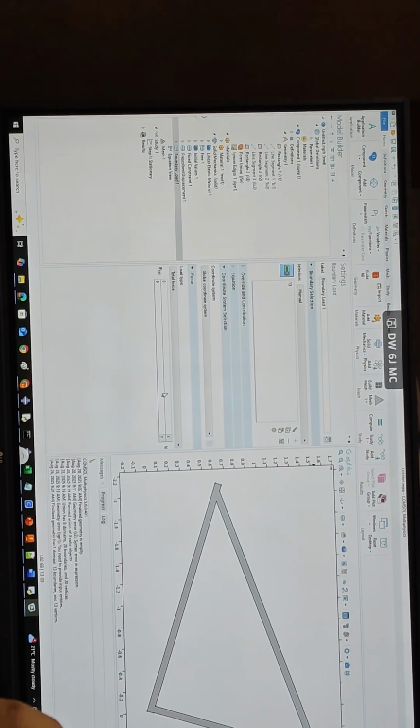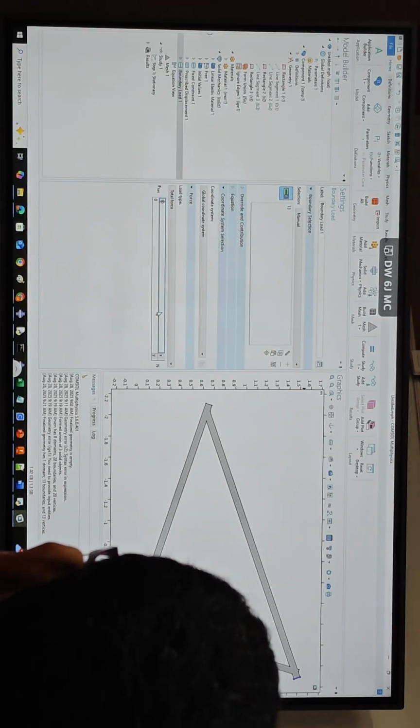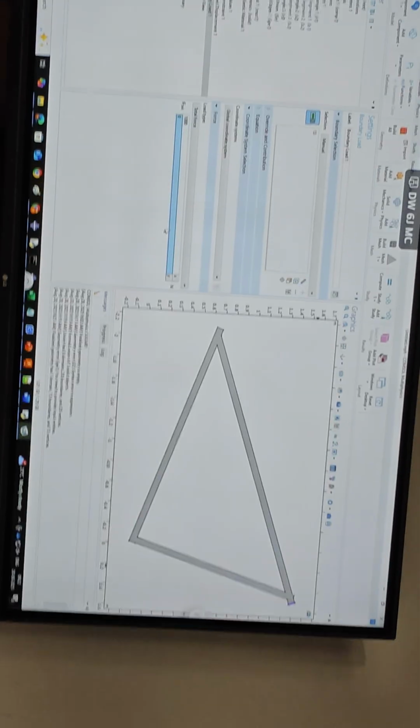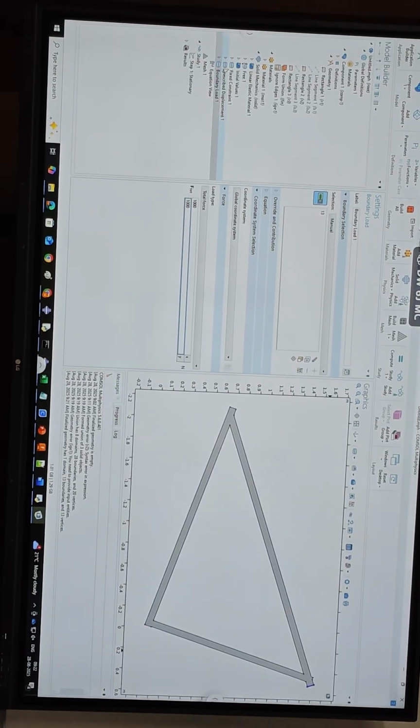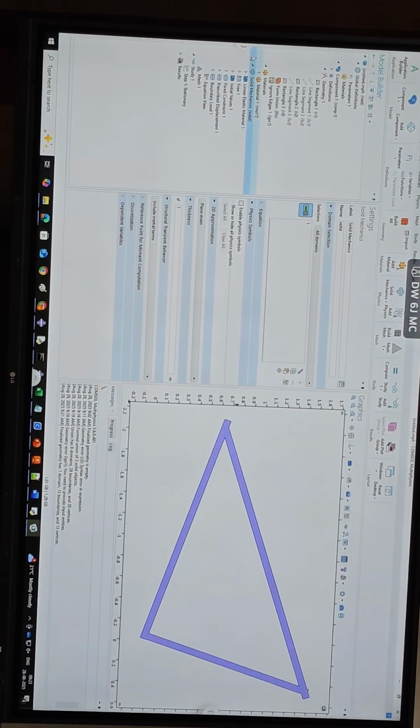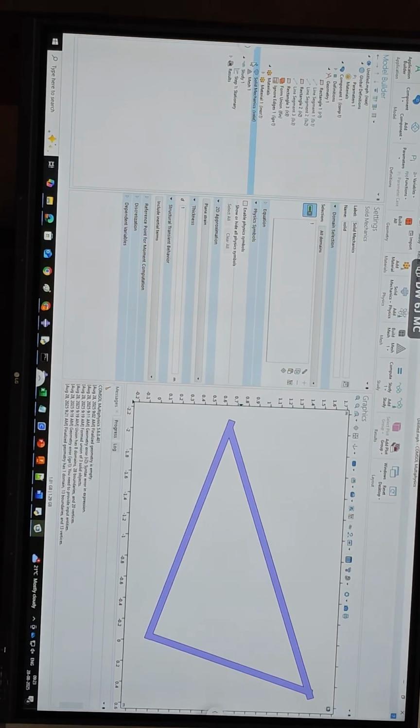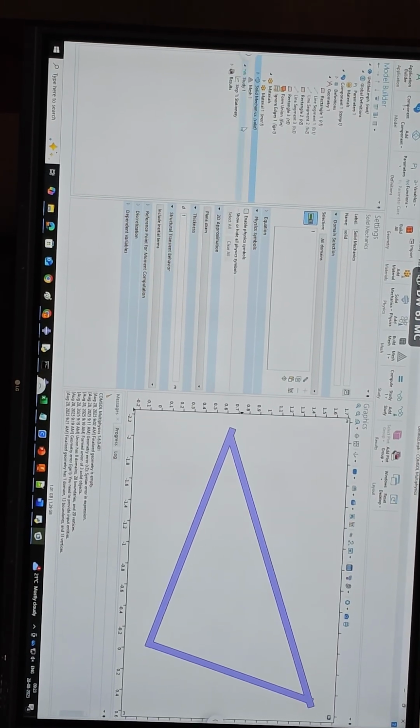And the last is the load. So the boundary load. So now we want it as total force, not as force per unit area. So total force, and then we'll select, let's say, this region here. So now it's 1000 in both the directions. So we'll give you 1000. So once we do this, the boundary conditions are done. So you can go ahead and close this. So now the out of plane thickness is given as 1 meter.